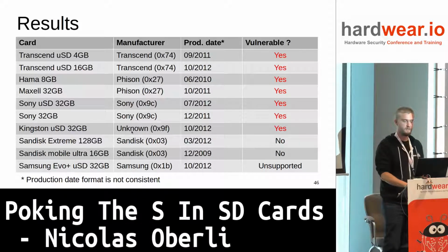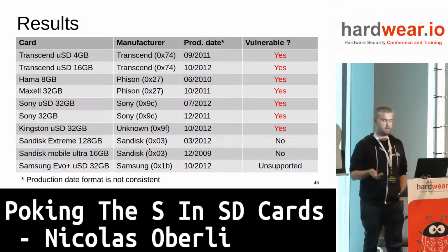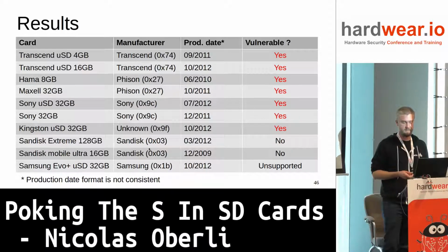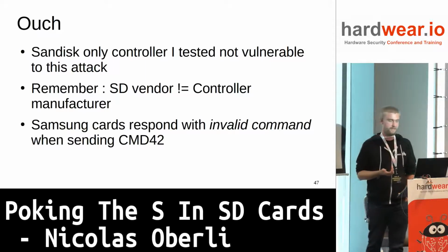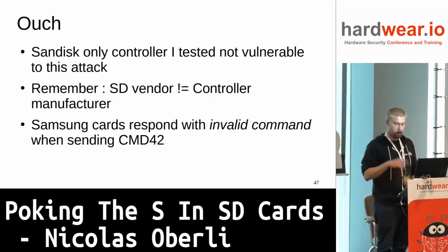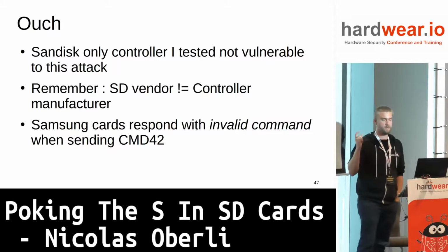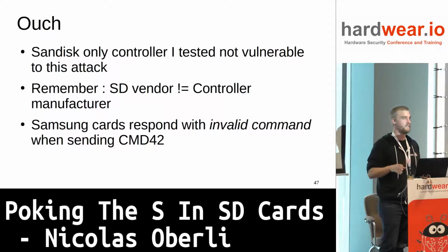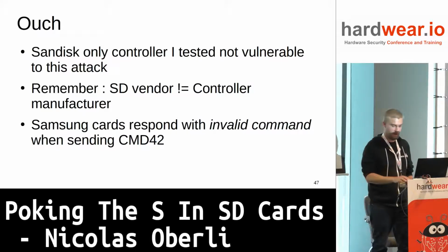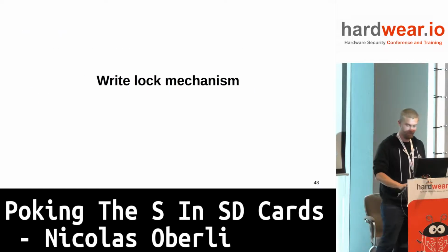As I said, I found all the cards from Tencent, Phison, Sony. This one I don't know who it is because it's not written. There's no list of the vendors on the SD website. And the only card I found that was not vulnerable is the SanDisk one. A funny thing is that the Samsung card I have, when I send this CMD42 command, the card responds to me that this is an invalid command, it does not exist. So I don't know how they get the SD logo, but whatever.